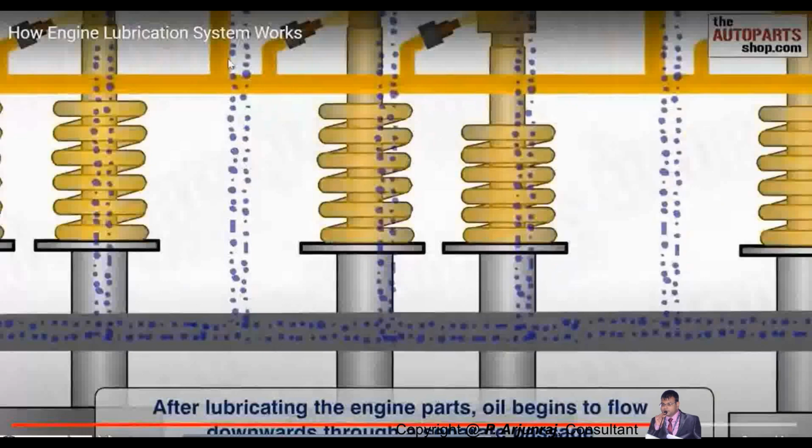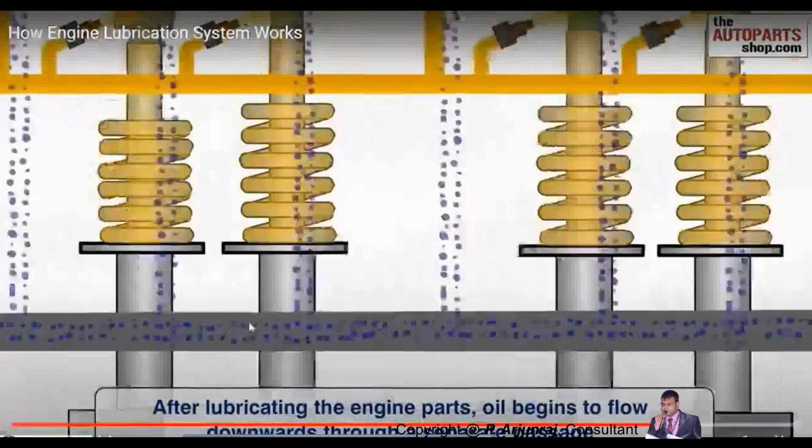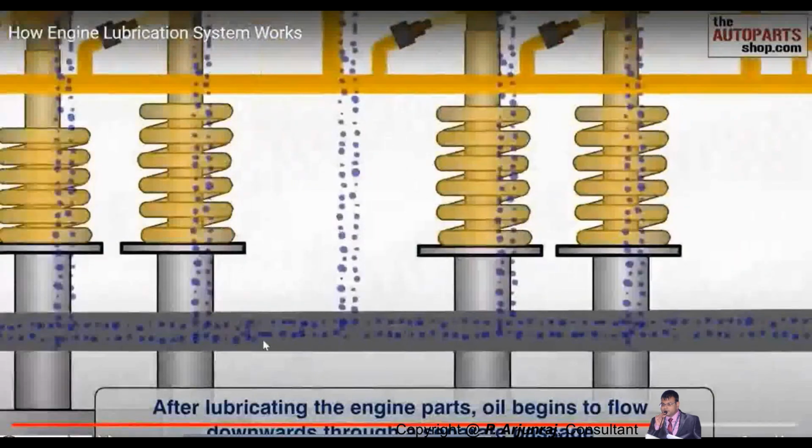After lubricating the engine parts, oil begins to flow downward. It goes downward, and there are separate passages there. One passage goes for the lubrication to the different parts. Another passage, after lubricating, the oil comes down and again goes to the oil sump.